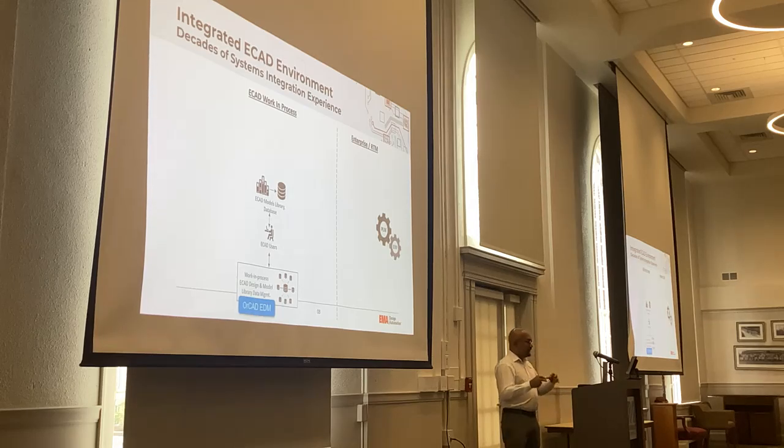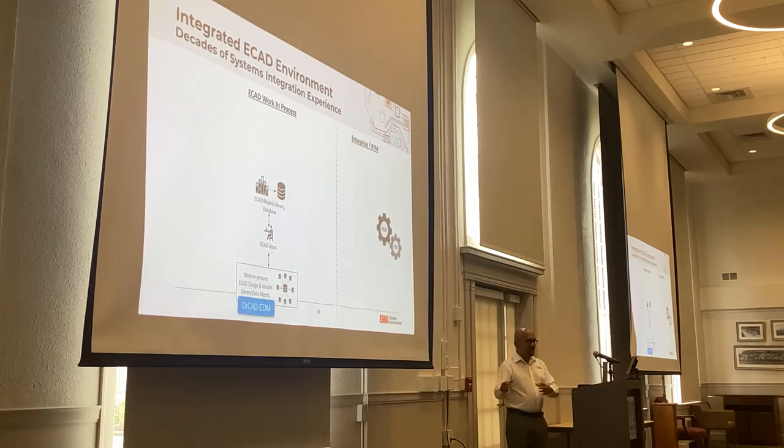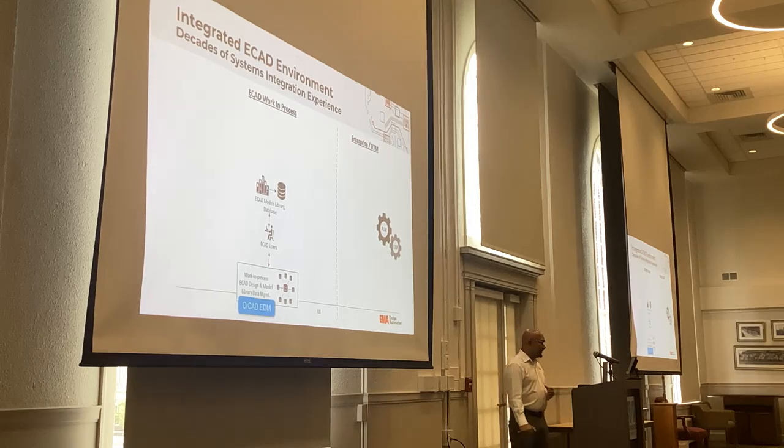Now we need a centralized CAD model library. This is putting all your schematic symbols, PCB footprints, 3D models, simulation models, everything in a centralized location, so that each user doesn't have their own library and then you're worried about cleanup a year from now. Having that centralized library for ECAD users in 3 parts, that's crucial.